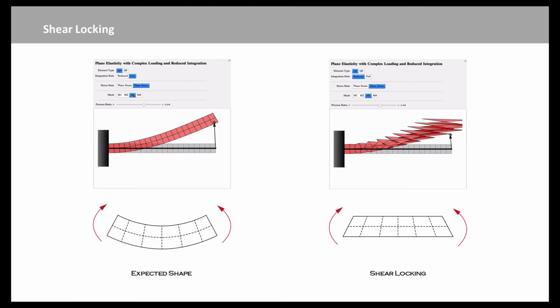Now if we reduce the thickness, the value of h cubed approaches 0 much faster than h, and as a result, all the strain energy of the plate will come from shear deformation. This is not correct because for a thin plate the bending deformations provide most of the energy, so the shear deformation can lead to wrong results for a very thin plate. This is called shear locking.